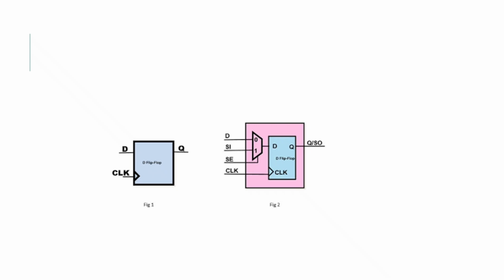Now, once the scan insertion is completed, we do the pattern generation using ATPG methodologies, using algorithms like D or PODEM algorithms. And then we simulate the patterns. It can be either timing or no-timing simulations, where timing simulation considers the delays. Then we hand off the patterns to the tester.